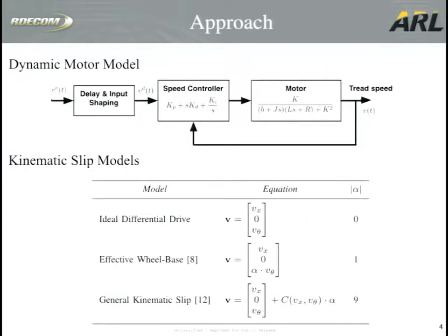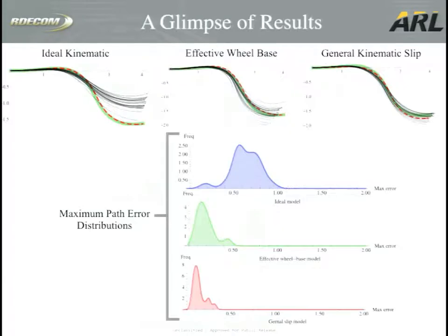We can use that data to fit a dynamic model for the motors, and we'll examine several different kinematic slip models of higher order. And then finally, we can use this to optimize control inputs and allow us to better track desired trajectories. And you can see some of our results here, and we'd be happy to share more with you at the interactive session.